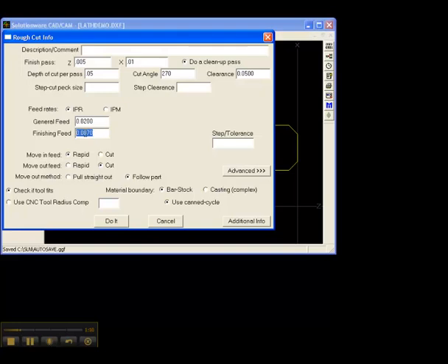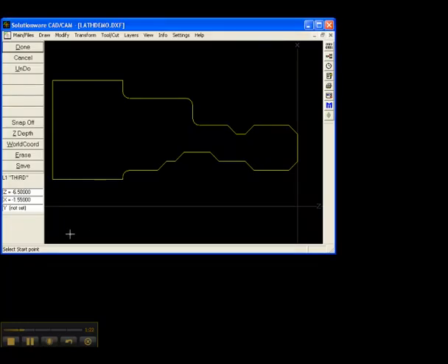This is the feed rate for the finish pass, I'm sorry. For Mazotrol, the finish feed is the rough box to the right of each of the shape lines in the process. Going on down here to the bottom, we're just going to hit Do It. And now on the bottom left of the graphics, it says Select Start Point. So for Mazotrol, this is the CPTX, CPTZ that you're selecting, as if you were doing a bar face.